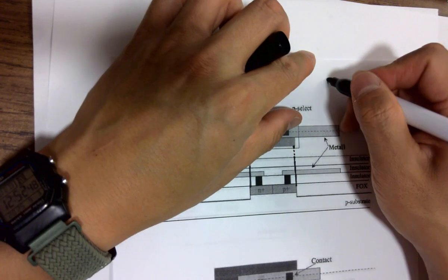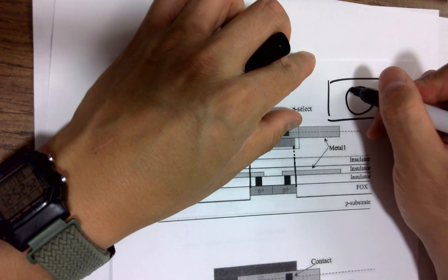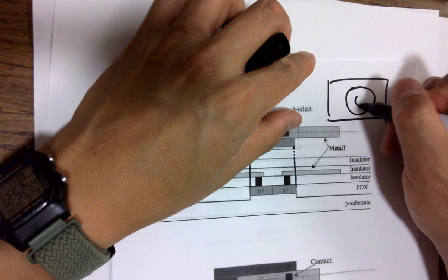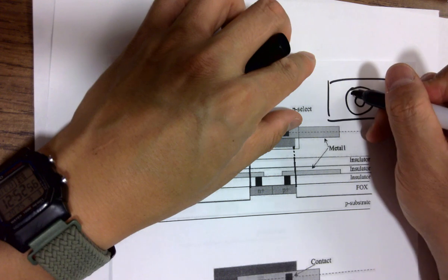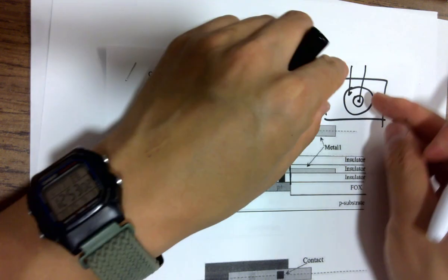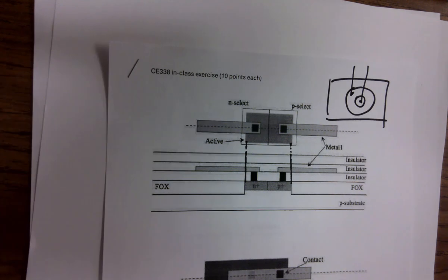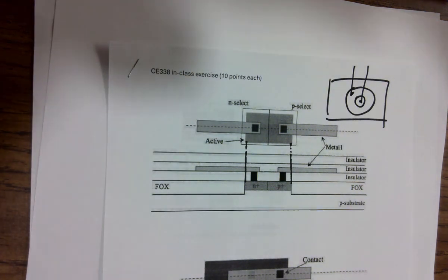So it's usually, if you look at the wafer like this from the top, right? You do a P plus first, and you dope N plus in the middle. Okay. I have a contact here and contact here, and a wire going up. Now this is from top. You can imagine it's going up. You know what I mean? So you dope a P well first, and then dope an area N plus in the middle of the P plus.